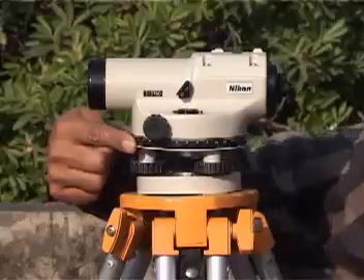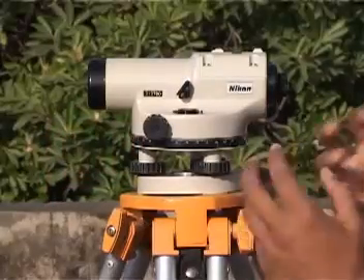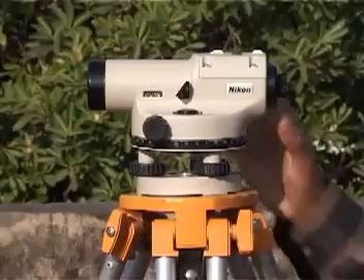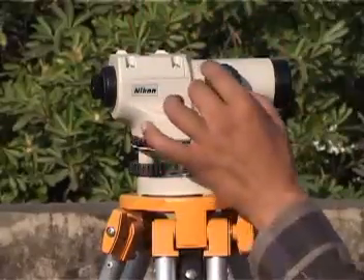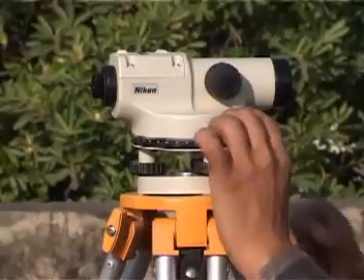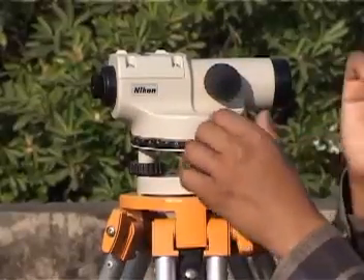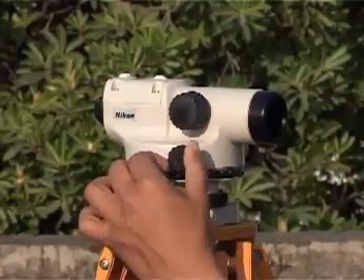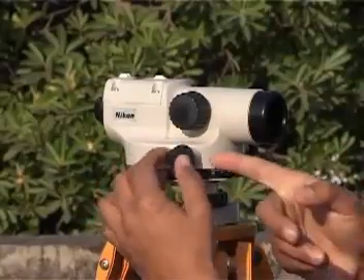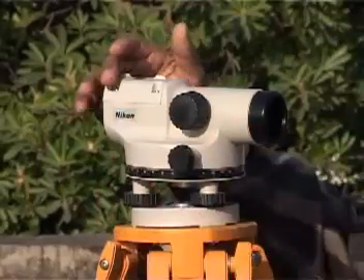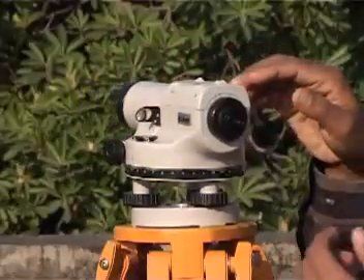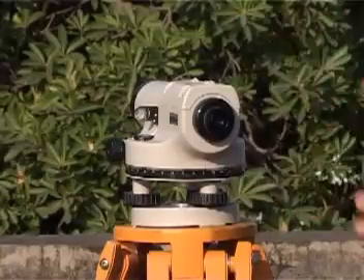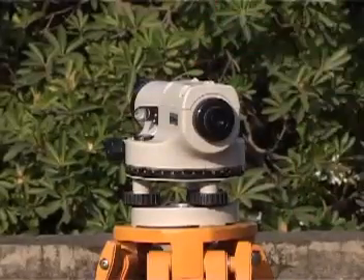Now these graduations here are 0 to 360, so it gives you an idea of measuring the angles also. Sometimes you can use it to measure the angles. Well, in this instrument, to focus the objective, and to give very small rotations, I can rotate it by hand, of course, but to give very small tangential rotations, we use these tangent screws. Similarly, as in all the instruments, we have the line of sight or the rifle sight here. So the initial sight that we take on our staff, we make use of the rifle sight.